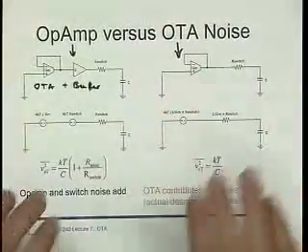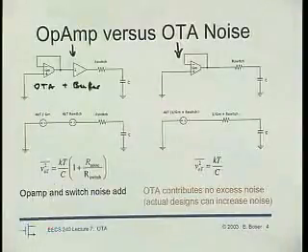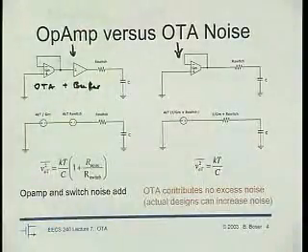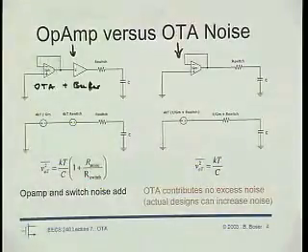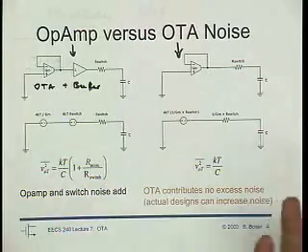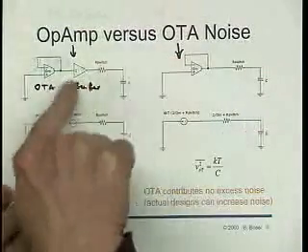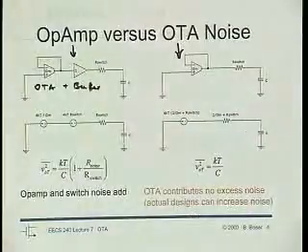On the other hand, there are some advantages, like we don't need extra elements to provide low output impedance, and especially at low voltage those are very hard to design. We'll look a little bit at buffers. Sometimes, of course, they're needed. If you want to drive an Ethernet cable, you had better put the buffer here. It's probably not going to work with just a transconductor.